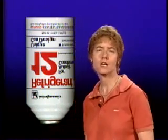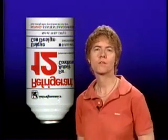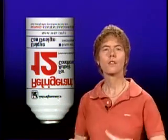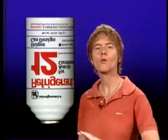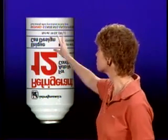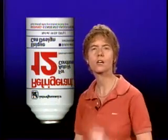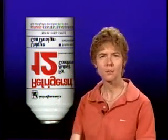Now, you can damage the compressor in a Freon system if liquid refrigerant is introduced on the low side of the system, if pressure is too high, or if the outside air temperature is too low. So you want to be careful about putting liquid Freon in, but if you are going to do it, the bottle needs to be vertical with the outlet down at the bottom.